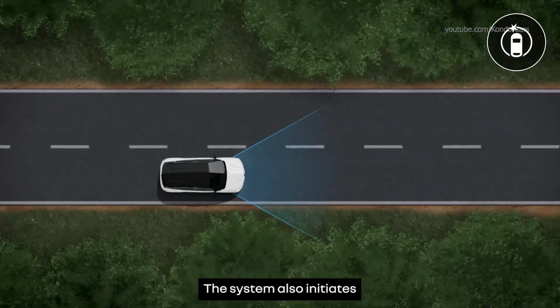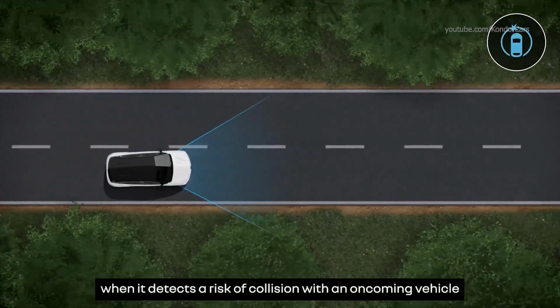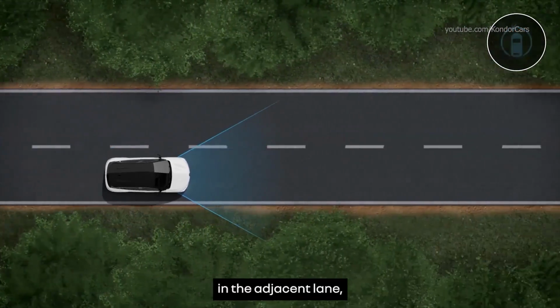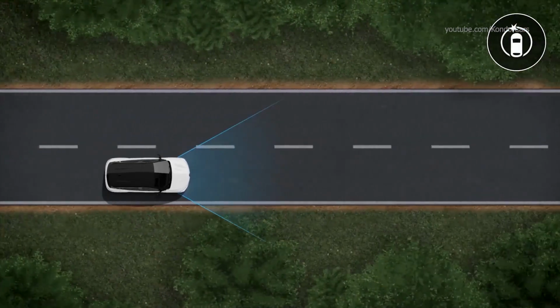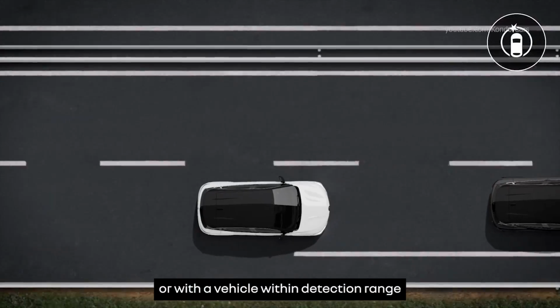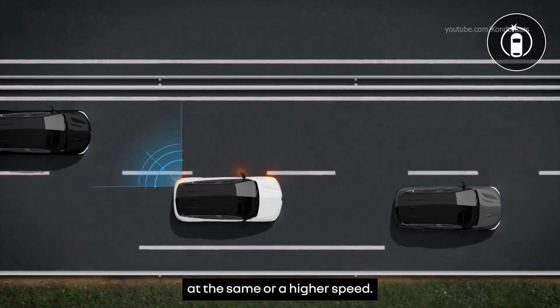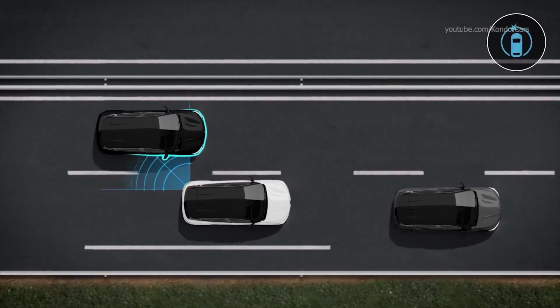The system also initiates corrective action on the steering wheel when it detects a risk of collision with an oncoming vehicle in the adjacent lane, or with a vehicle within detection range of the rear radar sensors that is traveling at the same or at a higher speed.